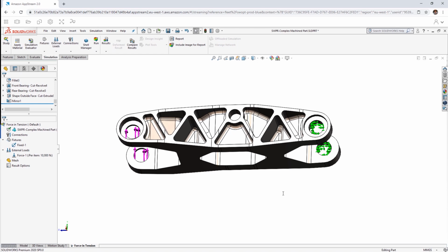Last step before we run the simulation is to define the mesh. Generally, this means two things. Have we got enough mesh to define the shape well? And is the mesh fine enough to show changes of stress and displacement? Because we don't know what the stress plot looks like before we run the study, sometimes that means we have to run the study predicting where we need to find a mesh, and then make iterative alterations depending upon the results.